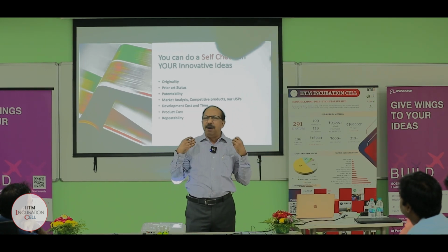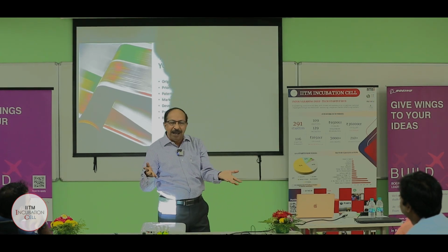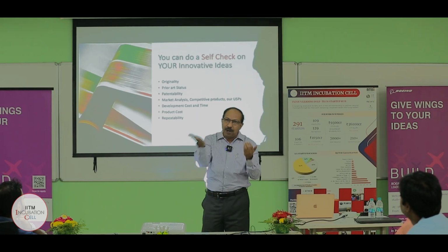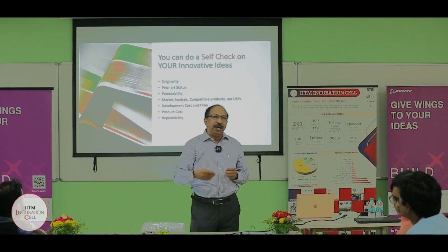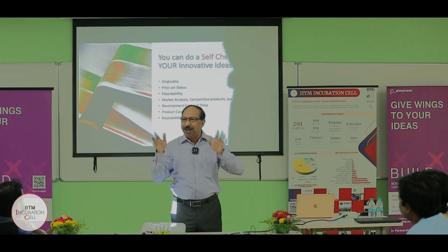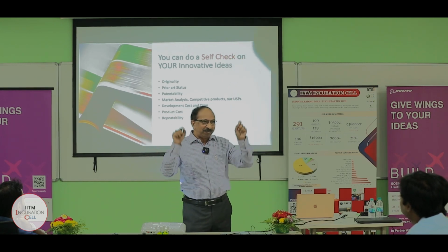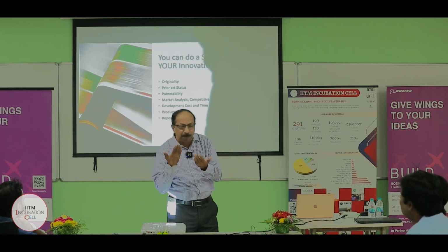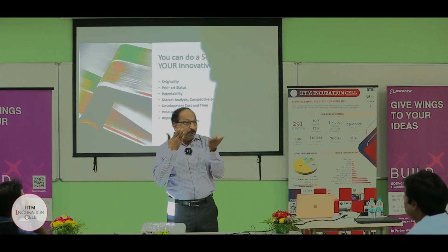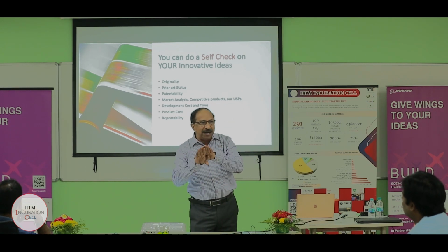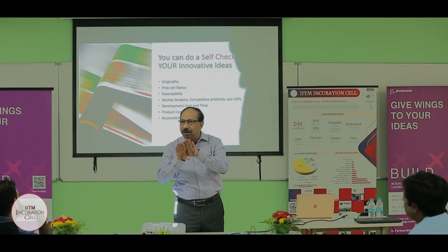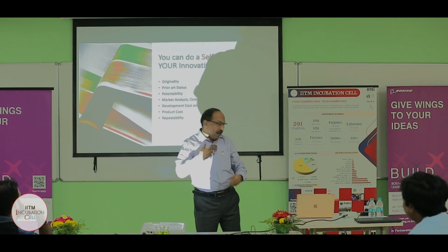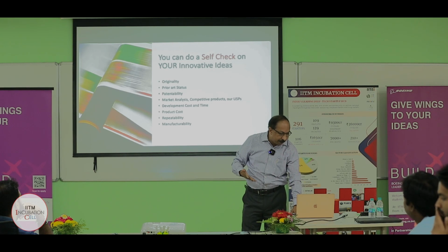So you may ask, okay, I will put a tight tolerance on everything. Then the cost will go very high. So you have to be very, very careful. Similarly, those who are in mechanical, in SolidWorks you can draw a very good cover and all, with no tolerance. But when you go for manufacturing, they will ask, what is the tolerance, plus or minus how much? So you have to give that tolerance. If two parts are there and the tolerances are not matching, it may become loose or tight or whatever can happen. So these are all to be understood very well when you are coming up with a product.